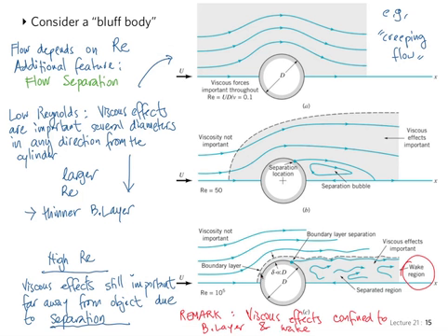Yes, but up to the boundary layer up to here, up to the point of separation, is similar to a boundary layer as we know it from the flat plate discussion. But beyond this point, it's what we call the wake, because it's no longer a thin region near the body. It's actually a very large region, and it's due to the fact that there's recirculation areas around here, because the flow is not able to follow this curved path all the way to the back.